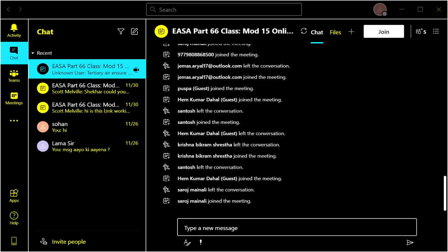And there it is. There's the system. You've got oil flow, some bits of metallic debris, and it will get picked up by the magnet. Again, they do vary in shape and size. Some are triangles, some are round for maybe single power systems, some are triangle for engine systems, some are just round in general. It just depends on the engine type, but they usually are colour coded. You're checking these as well. You'll have a bit of paper to write down the date, the time, the engine hours, the aircraft it came from, and that sort of thing. So you need a bit of information when you change these as well.